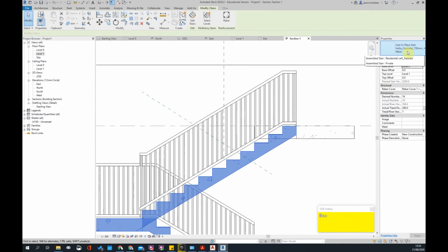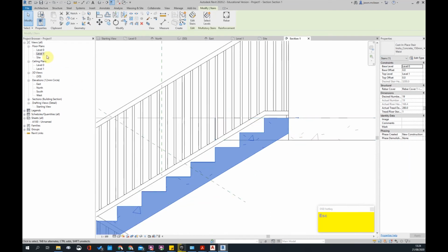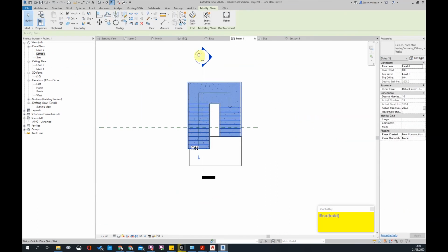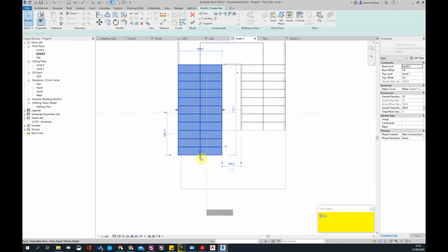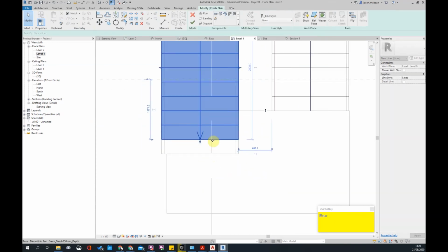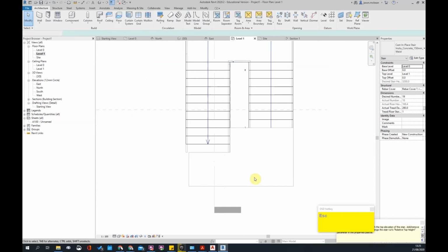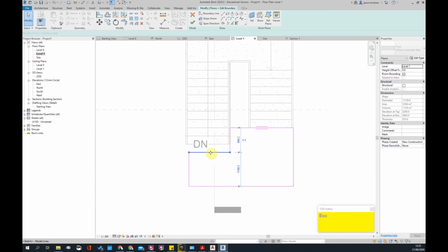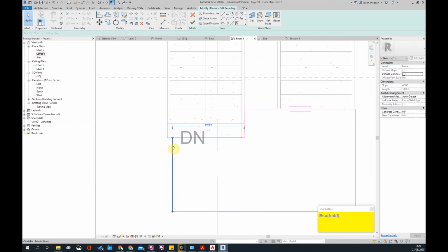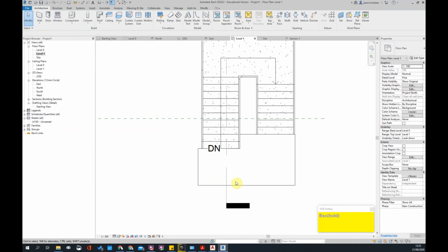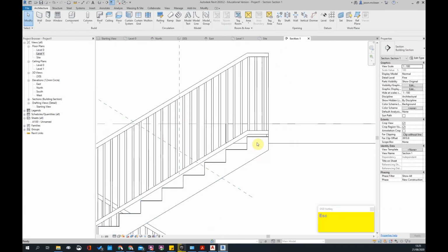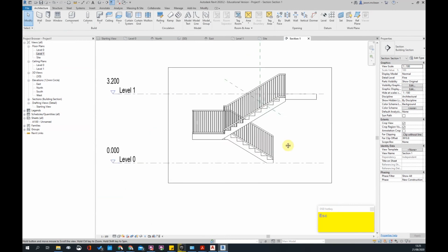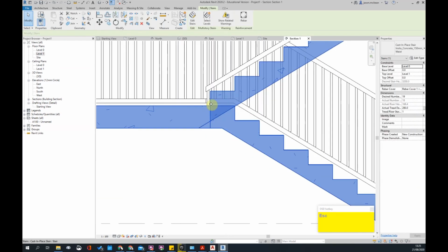With this type of stair where it's cast in place, I generally lose one of the landings because I pull this back. So here generally what I do is, I'm going to say edit stair, and I'll grab this guy and I'll pull it back once. Okay, finish. That's fine. Here I'm going to say edit boundary, and I'll pull this back to there. And I'm going to pull this back to the side. Generally I do that and then I use a fold region. And you see here it doesn't have a notch either.